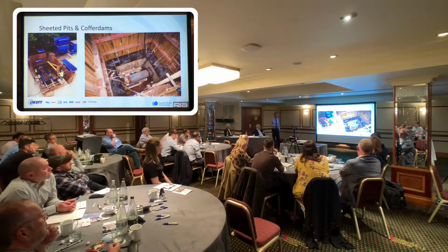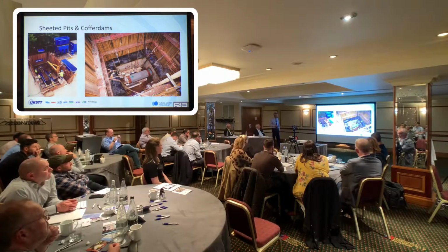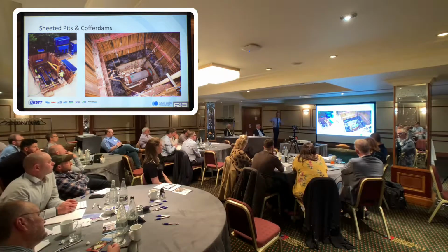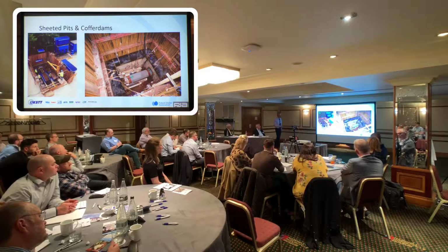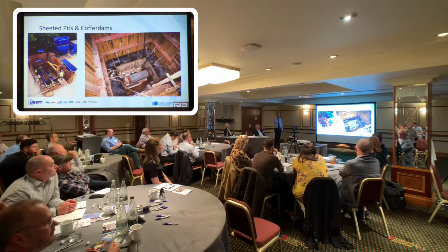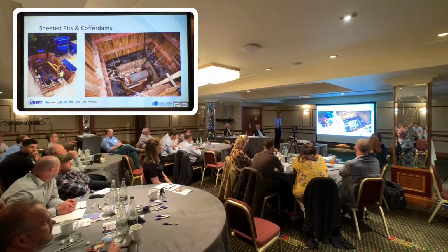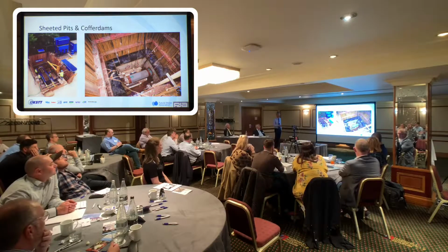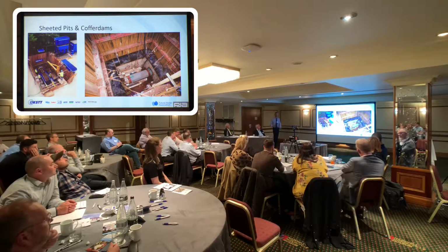And this is a sheeted pit that was sunk in rock actually, but for very good reason, because we didn't have room to actually get the right footprint with a circle. We've had to cut the corners off, and obviously we can't do that with a circular shaft. This is in a project in Albrighton, and it was a sewer replacement. So if you notice this black line here, that's a sewer diversion of a major trunk sewer above where we're actually tunnelling. So we had to go down, break that out, divert it around before we could even get down to the base here. And that's another reason for using sheeted pits, because it's a flexible support solution.